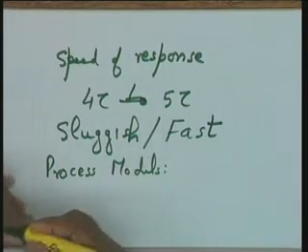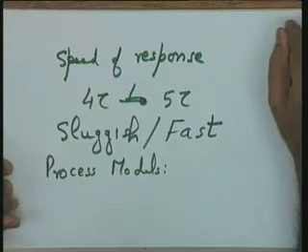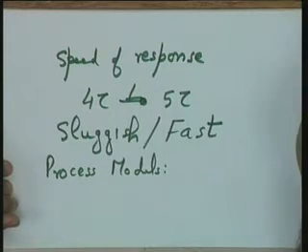Please see that the time constant of a typical system may vary from milliseconds to a few minutes. The example of milliseconds being that of the speed control system or a tracking system, the radar tracking system, servo mechanism for steering of an antenna, and that of minutes could be the temperature control and the like. So, you see that this is an important characteristic parameter of the system, the time constant, and 4 to 5 time constants gives you the total time for the system to settle down to the steady state environment.